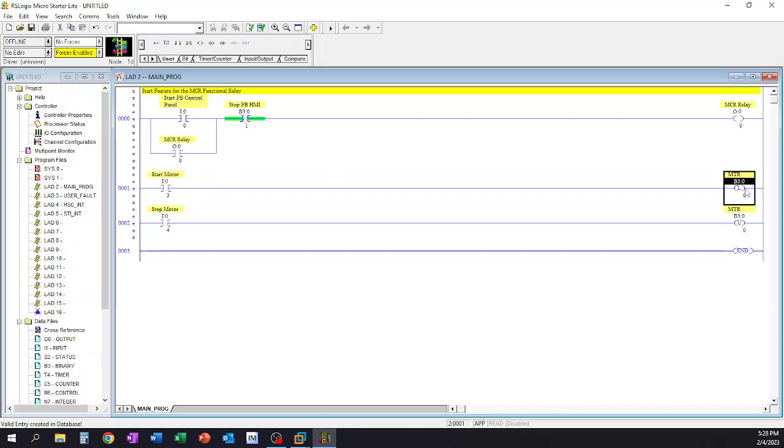One thing that'll always trip people up, and it has me several times in the past, is that when you look at this feature over here in a functioning program, you'll see both of them green, the latch and the unlatch green. Now that means that that particular bit is in the true state. So it'd be a 1 if you were to look at it as ones and zeros.